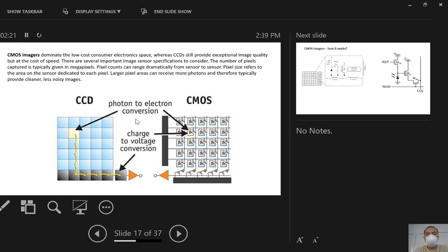And that's it. Usually the CMOS imager chip is slightly bigger than the other dies we have, because you need a relatively larger area to receive enough photons and to host all these millions or billions of pixels. Every pixel has a photodiode and a little capacitor. You can imagine you have millions or billions of them on one single chip.